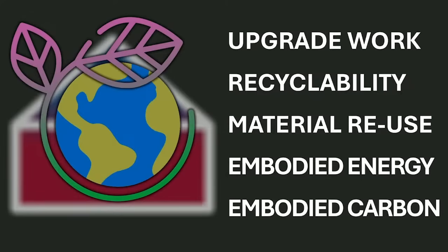In most cases, all types of roofing underlay are heavily punctured with a variety of fixings during installation, so such systems are unlikely to be suitable for reuse once installed. Polypropylene, which is a commonly used material for roofing underlays, is an easily recyclable type of plastic. Such plastics are also less hazardous and potentially polluting as waste material than bitumen-based underlays. Some commonly used materials, particularly traditional felts and some types of roof covering, may require specialist disposal during demolition to be safely reused or recycled.